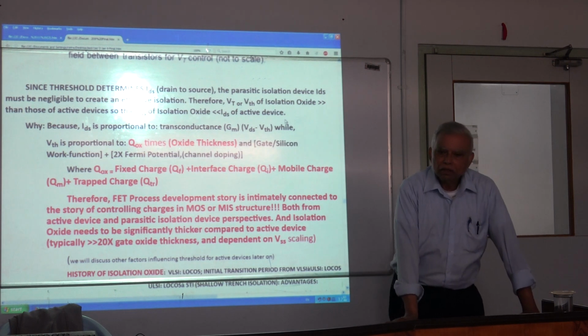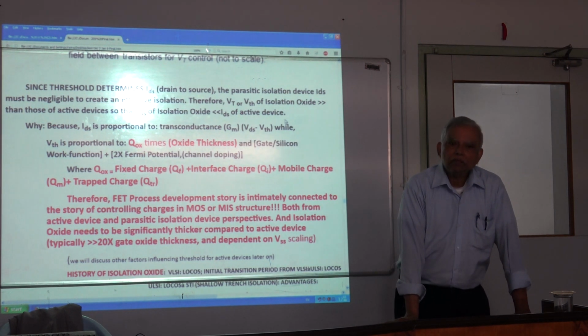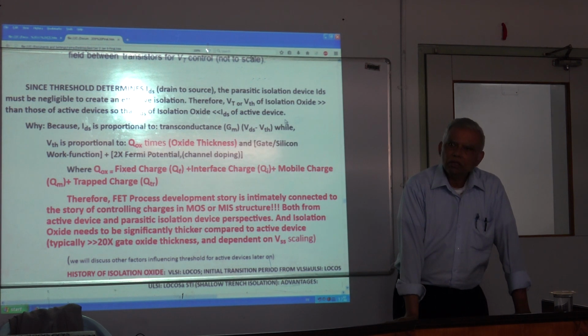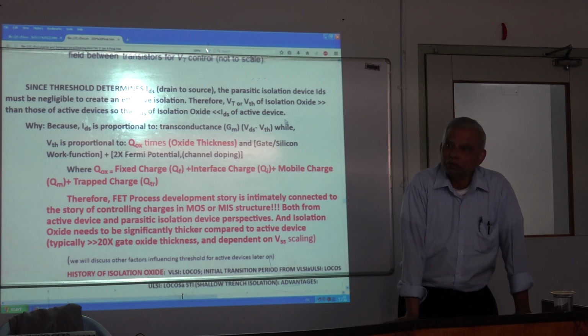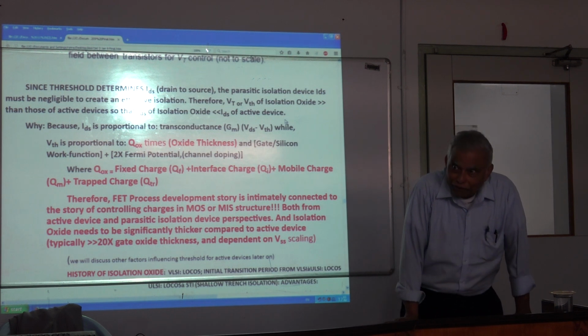If you don't design that properly, you can introduce during operation a certain amount of leakage, because it's also acting like a parasitic field effect transistor, sometimes in series, sometimes in parallel to the circuits.